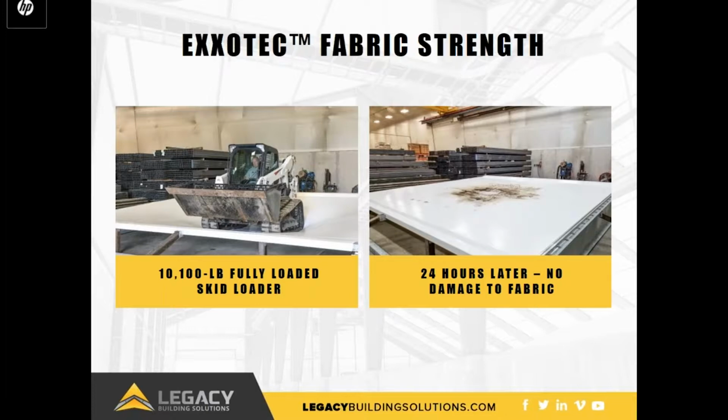To demonstrate the strength of the fabric, Legacy placed a skid steer loader with a snow bucket on a sample of our EXXOTEC Elite fabric. That's the CEO of our company driving the loader. And as you can see, the fabric combined with the attachment system supported the full weight of the skid steer loader, which was over 10,000 pounds. The next day, the fabric showed no signs of damage, besides being a little bit dirty. If we tried to do this with a steel panel, we would have had a significant skid steer repair bill.